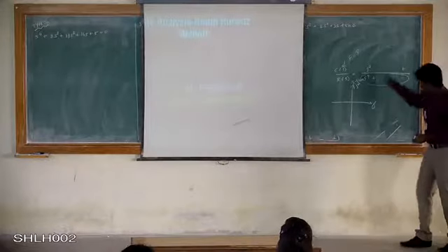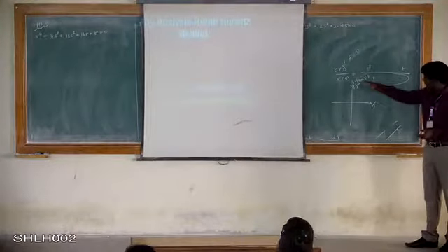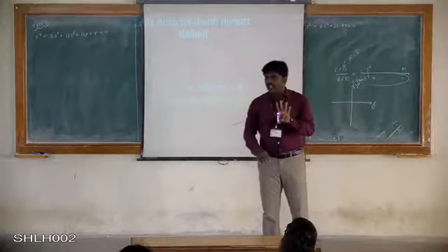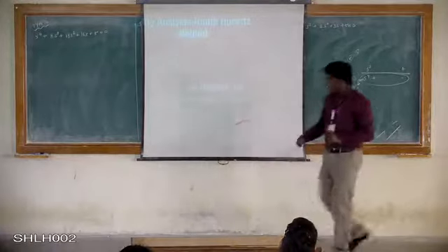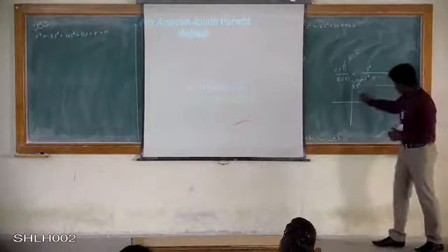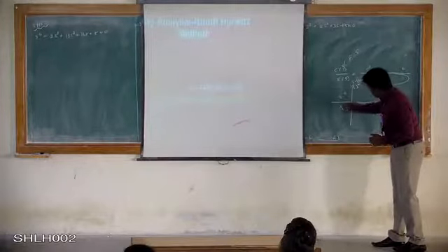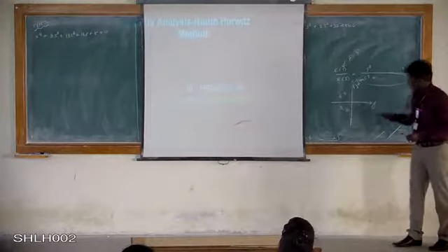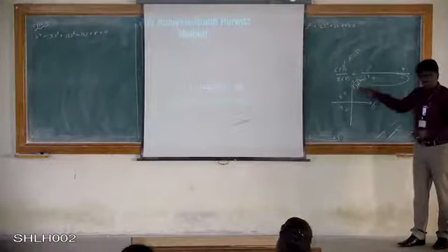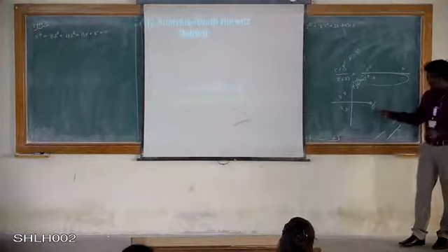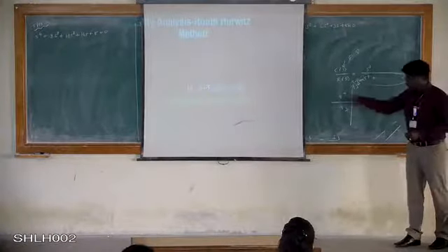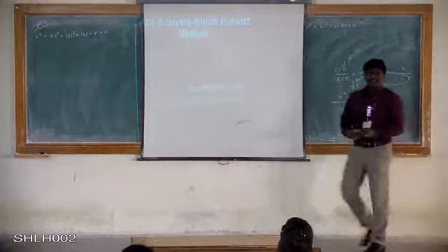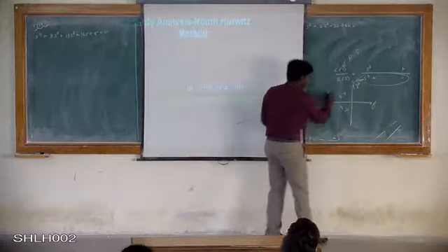Okay. So now when you solve this particular equation, as you told, it is a fourth order equation, so you will have 4 roots. If you get these 4 roots, and all these 4 roots are lying on the left side of the S plane, with imaginary axis j omega and real axis sigma, then your system is stable.